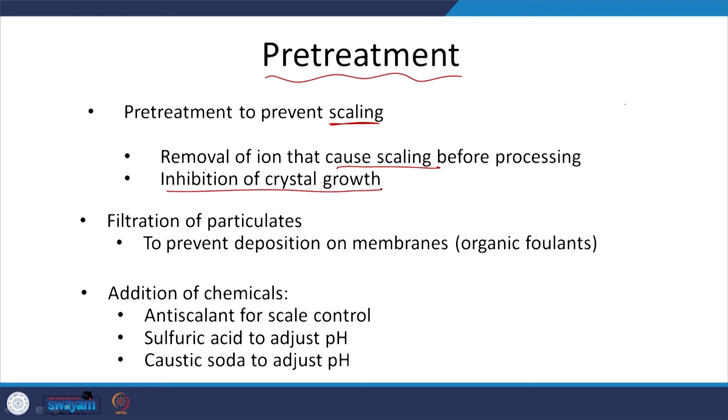In precipitation, there are different stages. One is nucleation, the first step, and the next one will be crystal growth, and then agglomeration and so on and so forth. So, you can look at various ways to minimize crystal growth. One is obviously concentration, one is surface area, turbulence and such. So, that is one aspect to keep in mind.